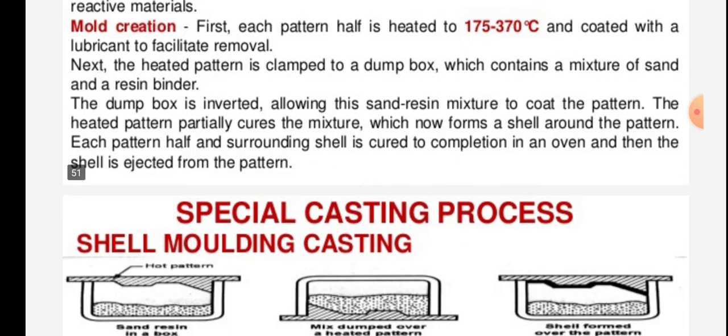The dump box is inverted, allowing this sand resin mixture to coat the pattern. The heated pattern partially cures the mixture, which now forms a shell around the pattern.